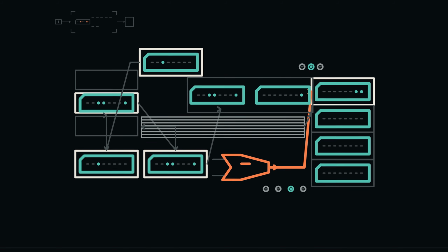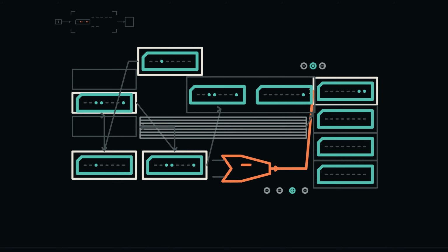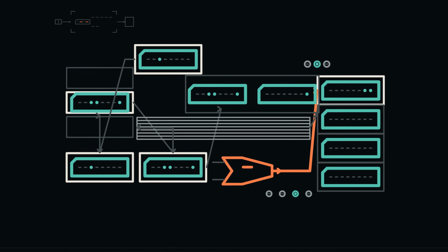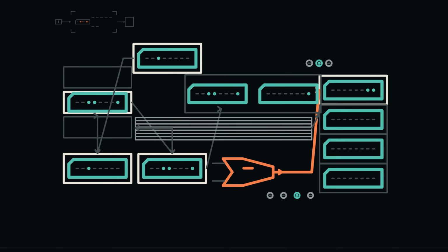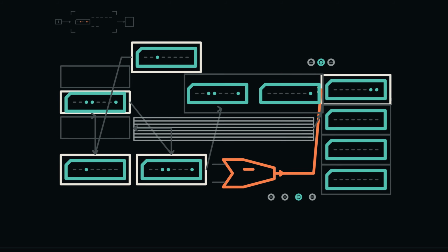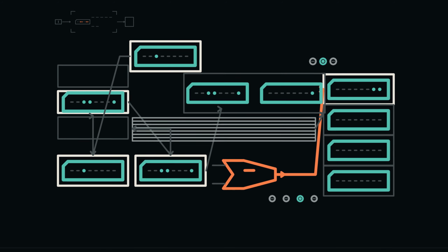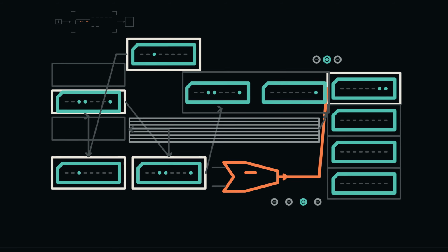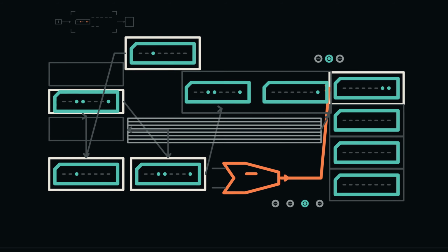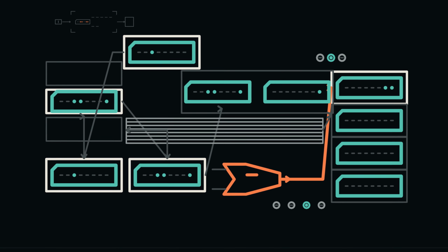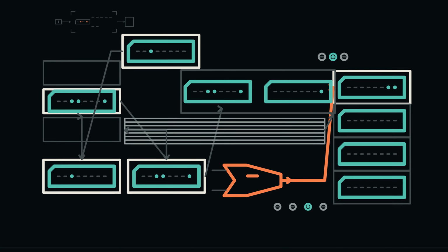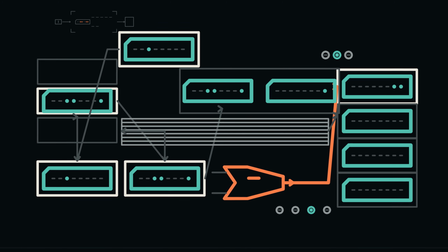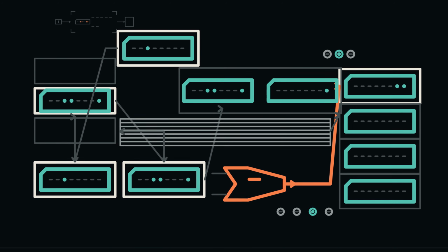The shared bus is a temporary route, not another storage place. During one transfer, exactly one source is permitted to drive it and exactly one receiver is told to capture. When nothing is transferring, the bus is marked invalid. An idle route does not secretly carry 0. The controller advances through named states that open one route, commit one change, and then close it. Think of railway points only for the idea of selecting one permitted route at a time. No train is hidden in the circuit, and the comparison ends there.